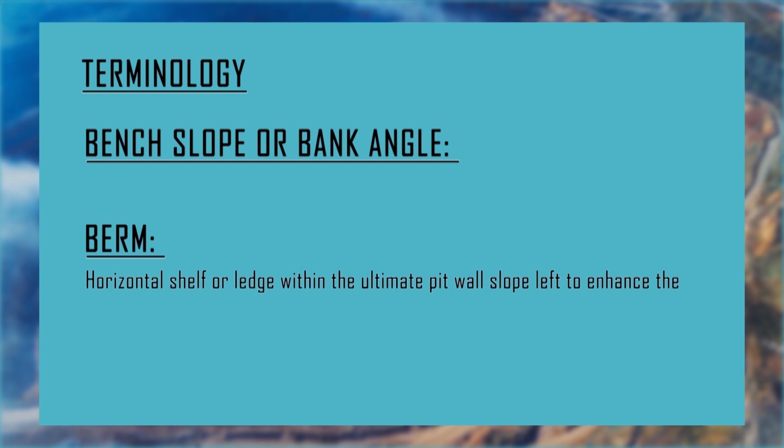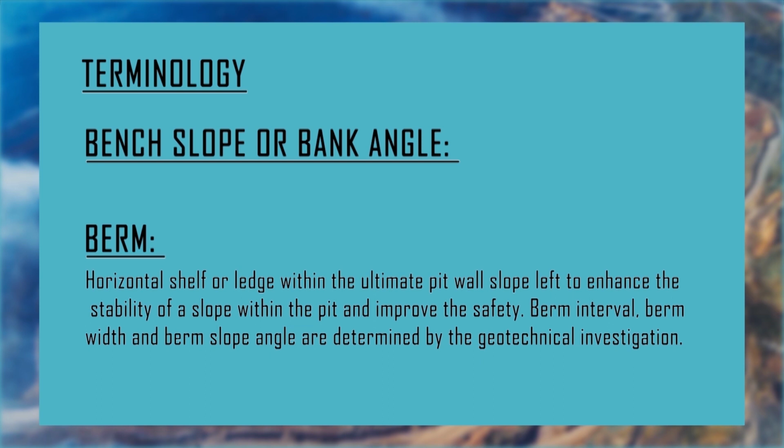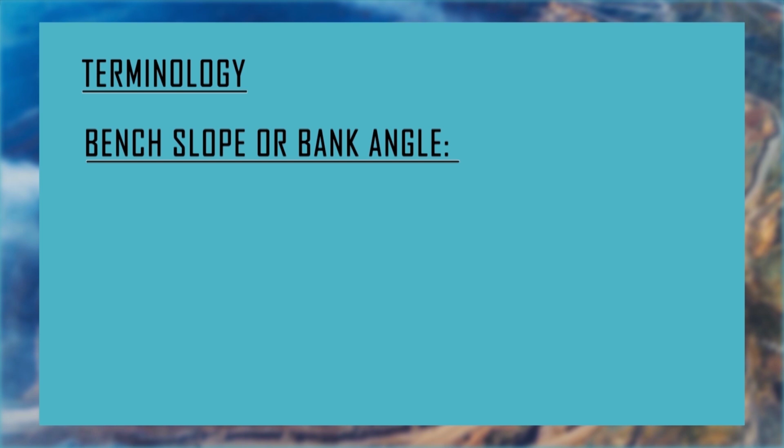And this is the berm. Berm is a horizontal shelf or ledge within the ultimate pit wall slope, left to enhance the stability of the slope within the pit and improve safety. Berm interval, berm width and berm slope angle are determined by geotechnical investigation. Basically, berm is here regarded as a safety berm. It is placed at the corner of a bench or a ramp to prevent the falling of heavy vehicles that move over the bench to the haul road.